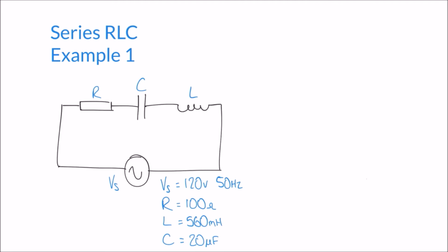First of all, we have our resistance, which is going along here, and R is, in our case, 100 ohms. So I'll put that on my diagram as well. We've also calculated our inductive reactance, which was 175.93 ohms. So I'll pen that on here. XL is 175.93 ohms.